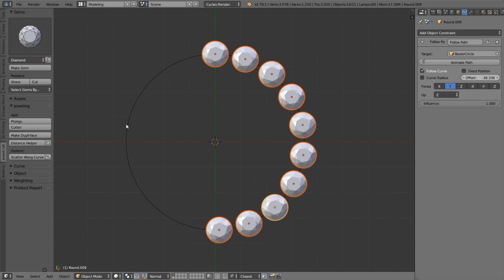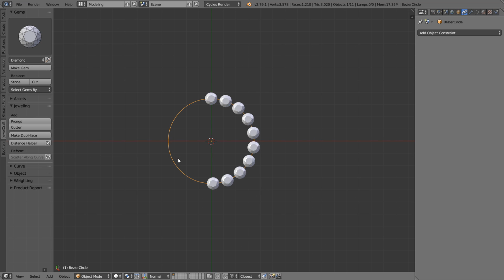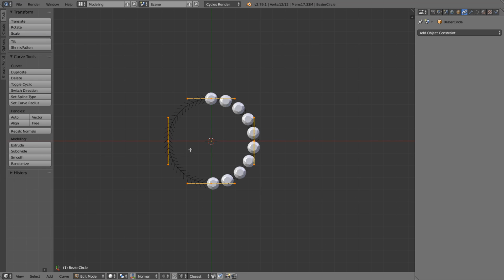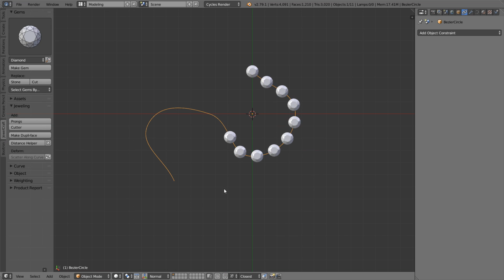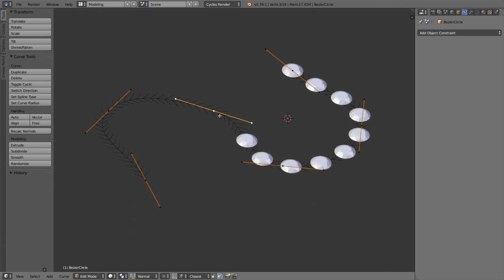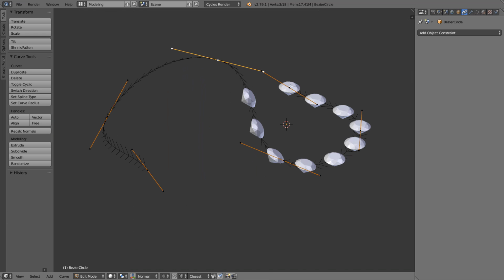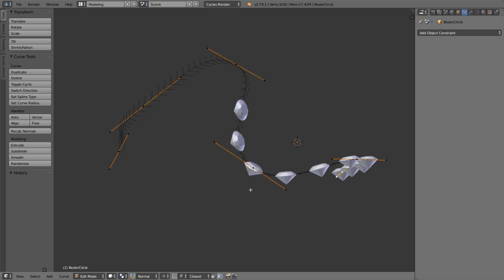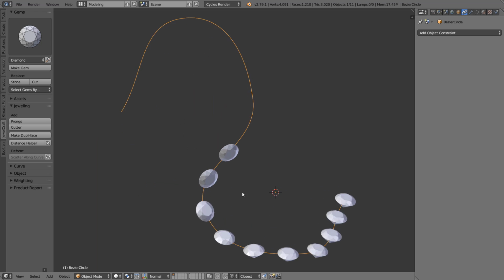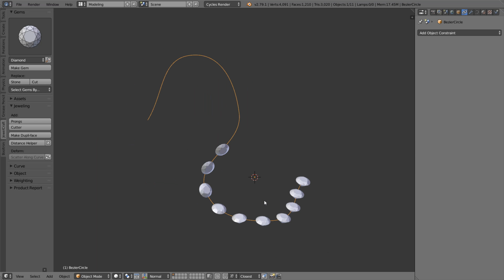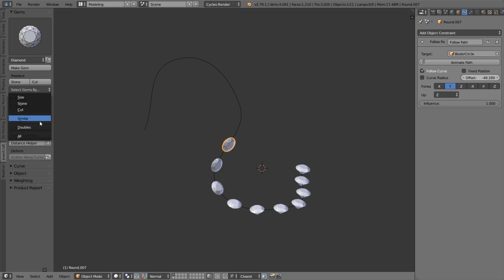Same as with duplicates or modifiers, stones scattered with constraints copy deformations of the curve. But there is one thing. Even if we used absolute offset for distribution, the position of the stones will be affected by the curve's length. In other words, if we increase the length of the curve, the distance between the stones will also increase. In that case, the Redistribute tool will be most useful.